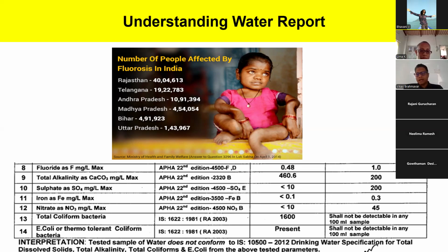Iron causes skin discoloration, things like that. So we should know the limit, which is 0.3 ppm for iron. In Bangalore, the Whitefield region and Ennore region have more iron in the water. The easiest way to find out is if someone adds chlorine, the whole water turns brownish in color. Or if you take a bucket of water and keep it aside in air for 30 to 40 minutes, it will slowly turn brownish. Then it means it has more than 1 ppm of iron, so we'll have to remove iron.